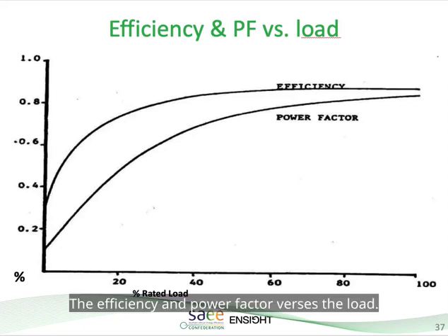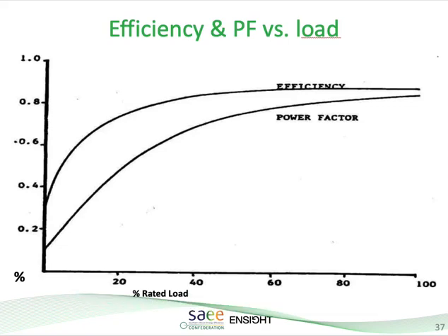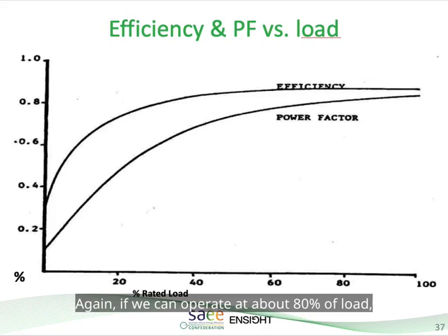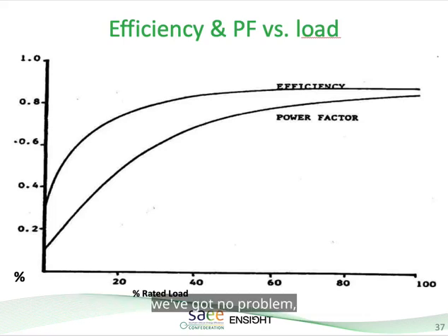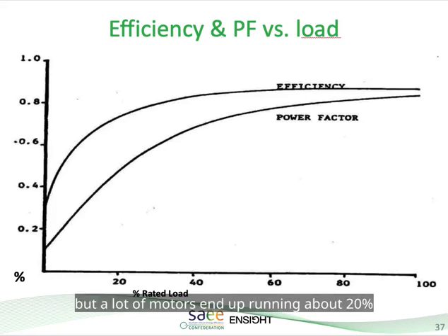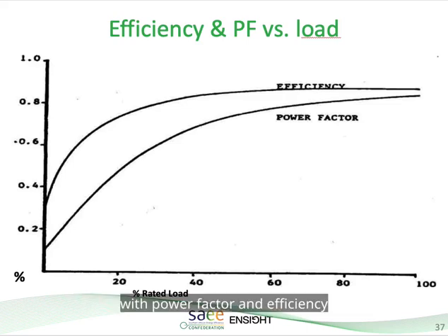The efficiency and power factor versus the load. Again, if we can operate at about 80% of load, we've got no problem. But a lot of motors end up running at about 20%, where power factor and efficiency start playing a considerable role, especially power factor.